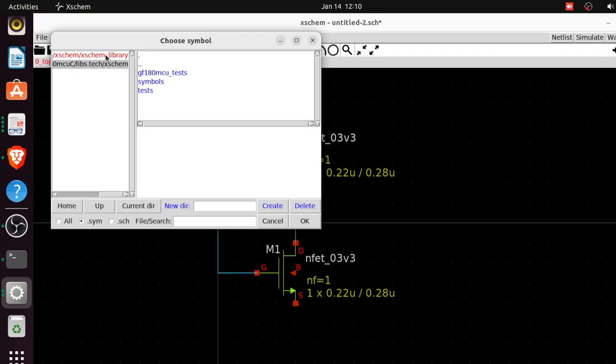Why those foundry specific devices? For instance, those are things you're going to be fabricating. I'm not going to be fabricating the voltage source. I'm just going to be using the voltage source for my simulation. That's it. So I can pick that one from scheme. But if I know anything would be part of my GDS file that I'll send to the foundry for fabrication, then I would have to pick such a device from the PDK library. I don't know if you guys get that.